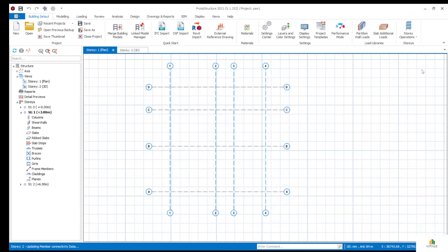Then let's say remove story. We have the remove story here. So maybe you have a story that you want to remove. The moment you click on the remove story, you see info, story. Then you see the story height, level, label one, two, description, D1, and those things. So if you want to remove a story, you select the info part. Then you click OK. Then it will remove.